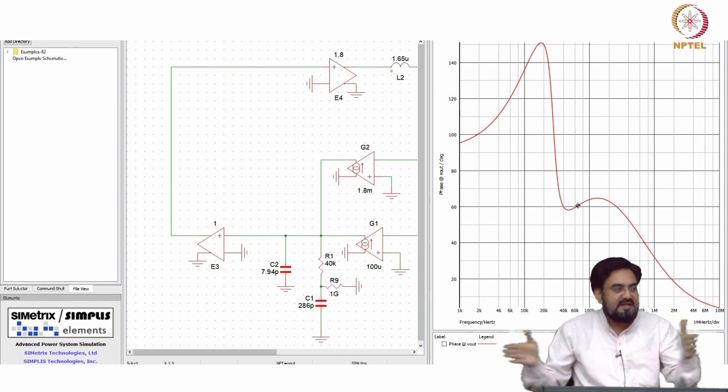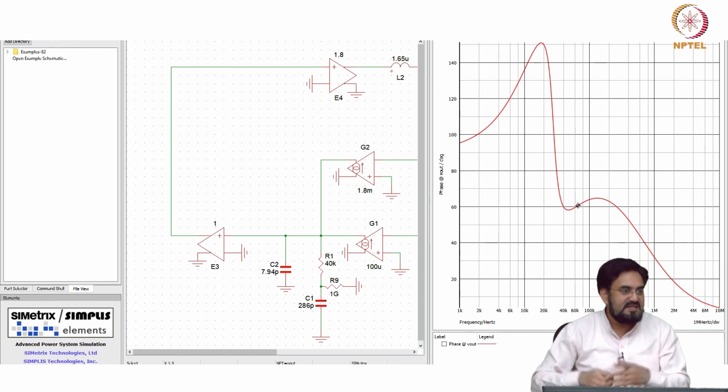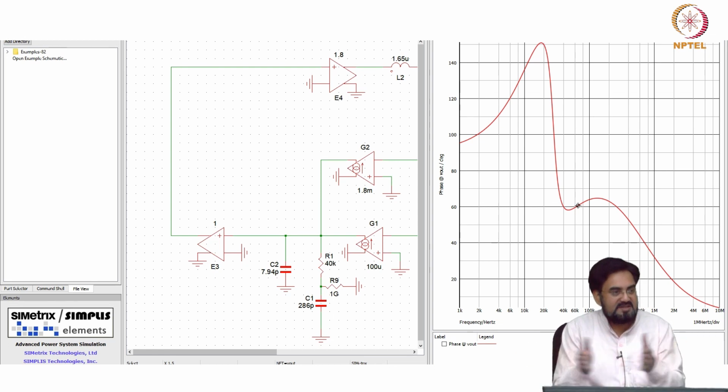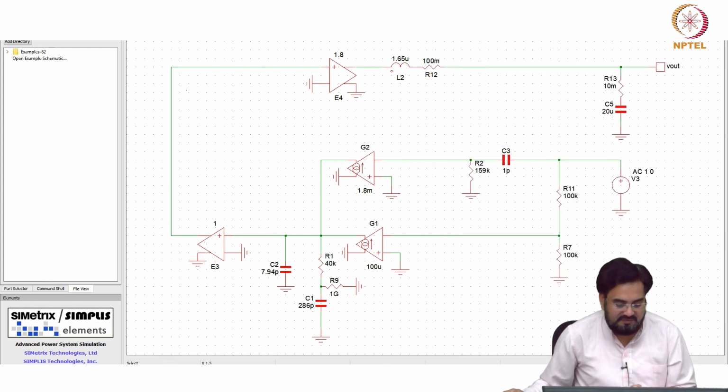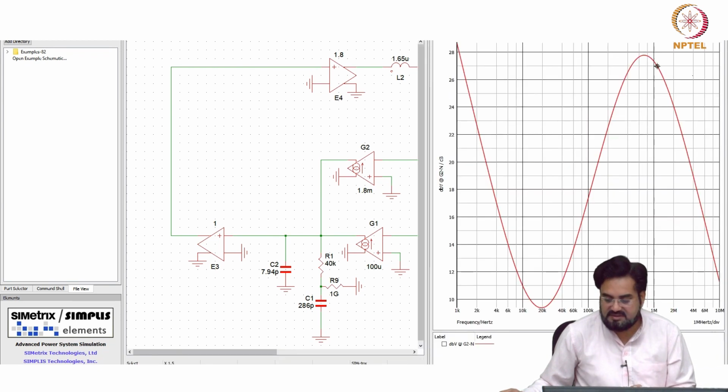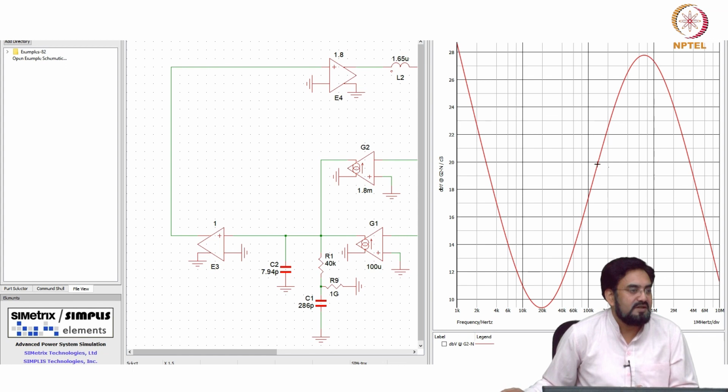So for a pretty wide range of frequencies, even if your UGB is changing due to loop gain or, let us say, PVT variations, your phase margin will still be maintained over a wide range of frequency, because this portion extends from omega naught until 3 times your UGB, which is good enough actually. And if I want to look at the output of this, you can see a similar thing.